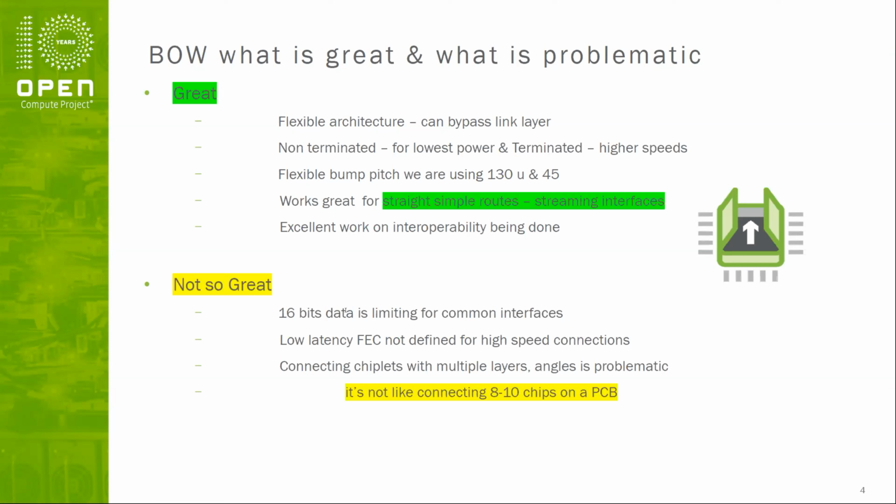And I just want to caution people that it's not like doing a PC board, where you just throw 8 or 10 chiplets on and connect them with these BoW advanced interfaces and everything works. It's quite challenging. So we're targeting very close connections, ideally direct.